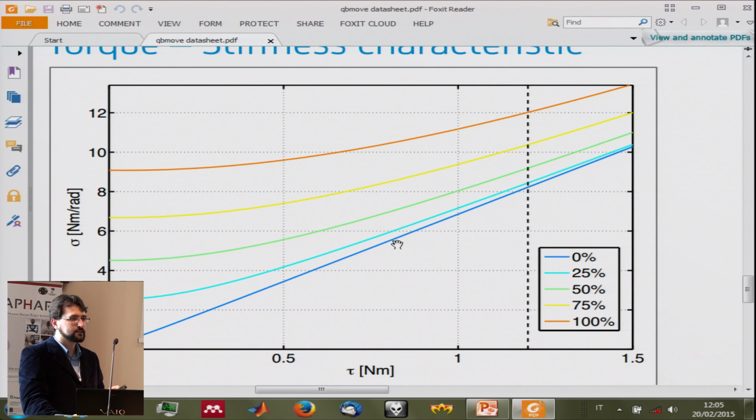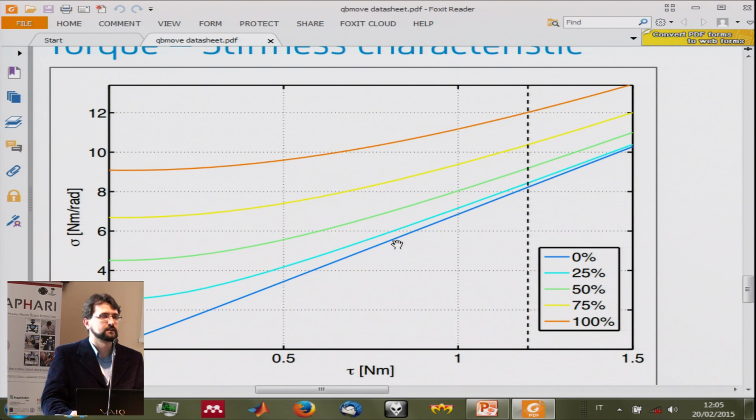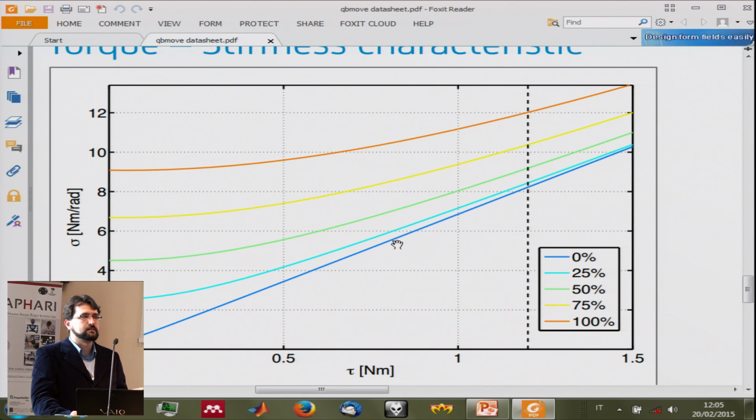Yes? So I see there are no torque sensors on the actuator. Yes. But is it possible to estimate from the current? Yes, you have the currents. The current readings are not always so linearly related to the torque, but it's something you can use. You can estimate the torque from the model of the stiffness. They are both estimates. Probably the better way would be to make some Kalman filter, sort of integrate all the information.